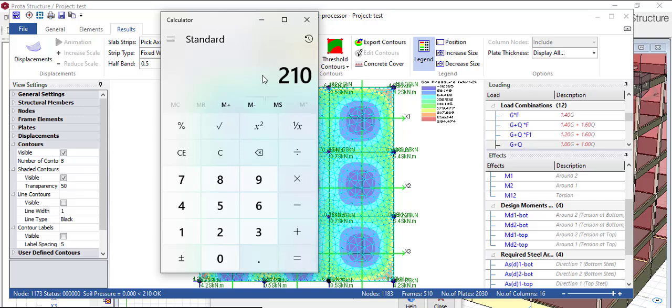So this is what it uses as your soil bearing pressure. Whatever pressure the building is producing, it equates it to 1.4 times the bearing capacity. So if it's less than 1.4 times the bearing capacity, then it's okay.